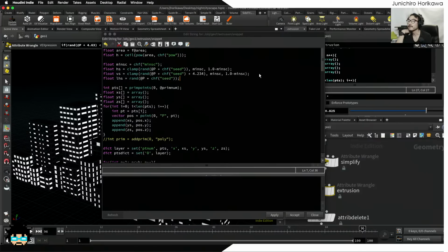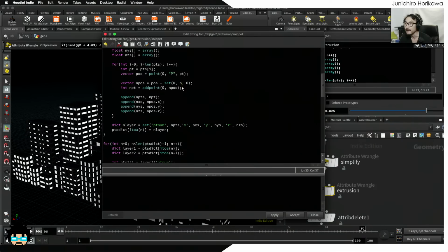No, the random creates the value from 0 to 1, but let's say I want to keep the height of the layer to be 1 as the default value, and just by multiplying it with some scalar value, I would like to change some values in between 1 to some upper value. So let's fit or remap the random value from 0 to 1 to 1.0 to 1.5, and multiply this value together with this n value here and see what happens.